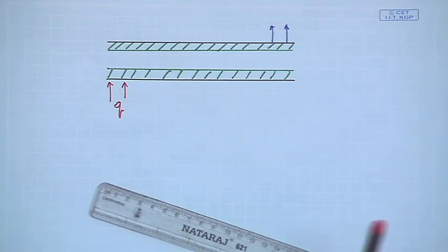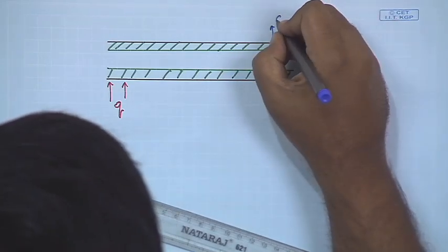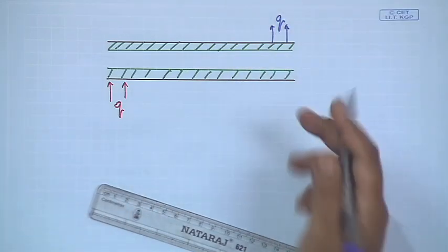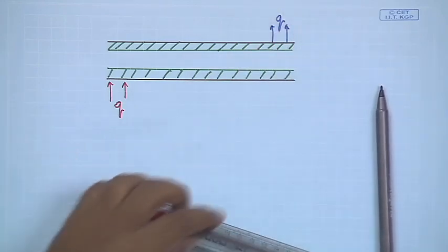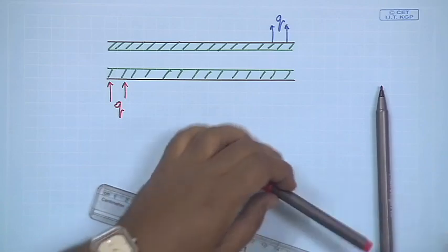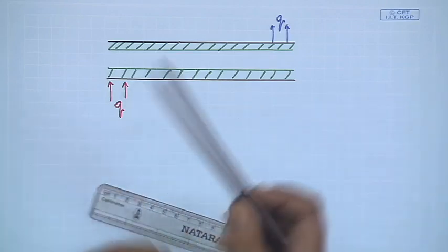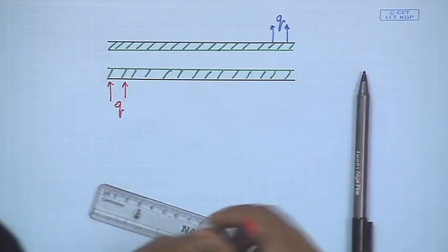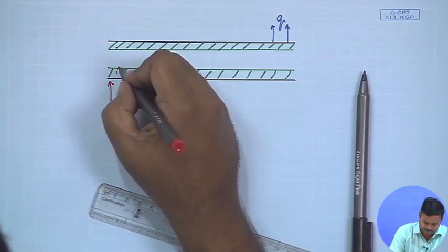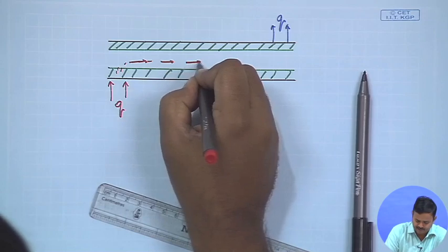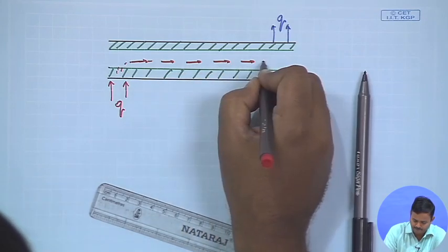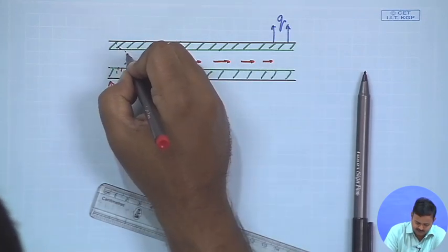So, here the heat is rejected by some means, because this end is kept at a lower temperature, and therefore what is happening is the water is converting to vapor over here, and then flowing through this core, and similarly from the other end also it will do the same.